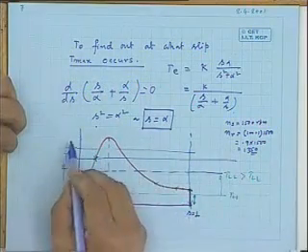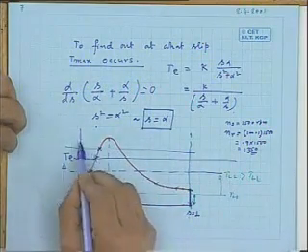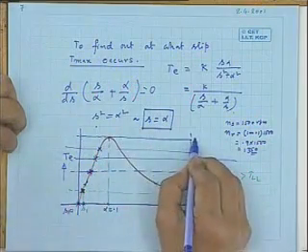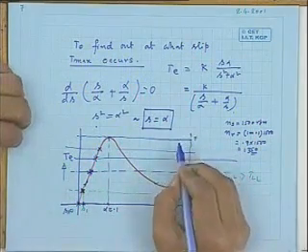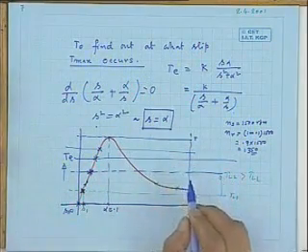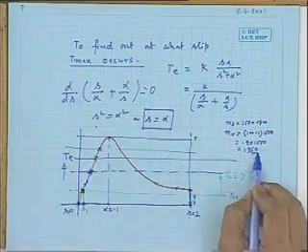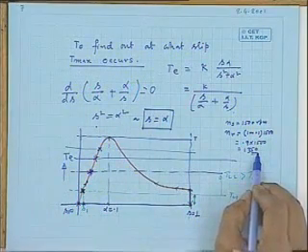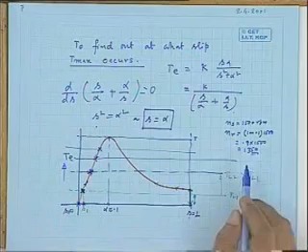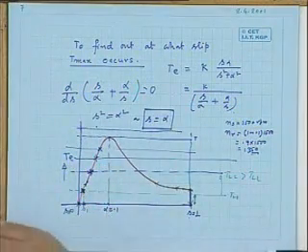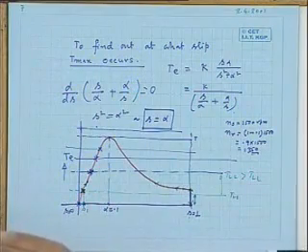Okay. Now what I am trying to tell, suppose in this way I am going on increasing the torque. The point will come here, like this. In this way, suppose I come here. The load torque is equal to the maximum torque the induction motor can develop. At what speed will the machine run? Right at this 1350 RPM. Now suppose beyond this point, I further increase the load torque. That is, I want to derive more mechanical power output from the motor. So I further increase it. Tell me, what will be the consequence?